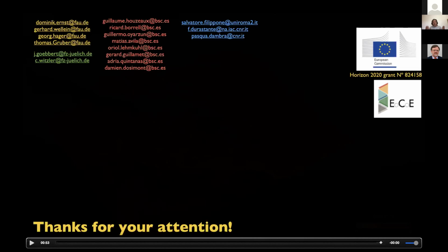If we want to do something related to RANS, here in EoCoE, at this moment, I am doing nothing with RANS. We are focusing all on LES, but we also work a lot with RANS, and we have this very nice collaboration with Iberdrola, where we use RANS simulation. This is the standard nowadays in the industry, and there the solver is very expensive. And in the future, we could try to do some RANS LES, put RANS close to the boundary to have something better than a wall model. And then perhaps this balance could change again.